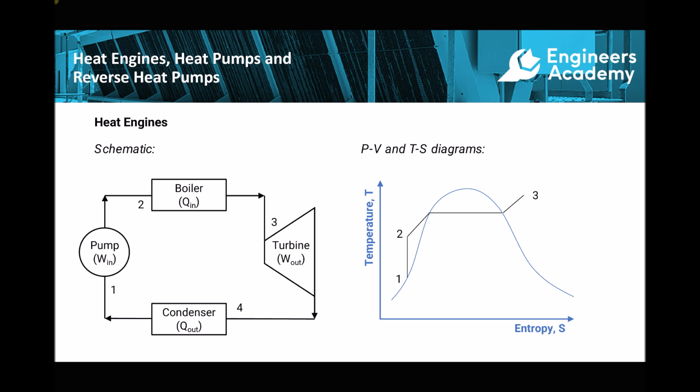Now a perfect illustration of this is if we're boiling water at atmospheric pressure, then we increase the temperature of the water to 100 degrees C. The water remains at 100 degrees C and begins to boil, and it will remain at 100 degrees C until all of that water is evaporated and becomes steam. If we were able to capture that steam and continue heating it, its temperature would begin increasing again, and then we get what's called superheated steam.